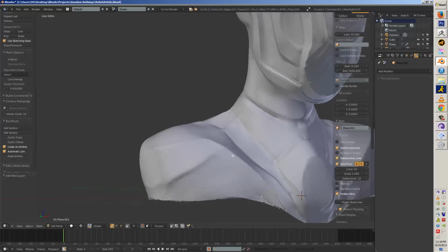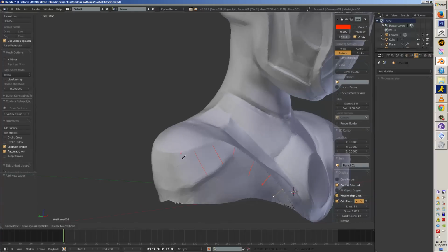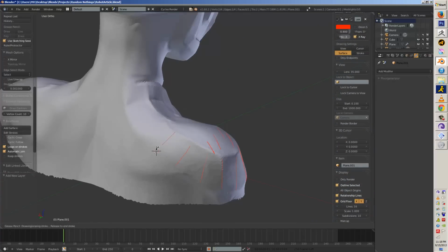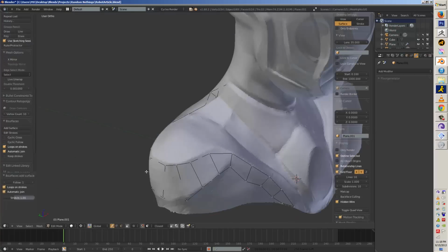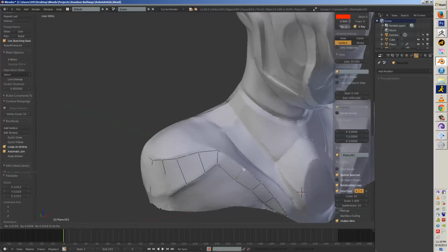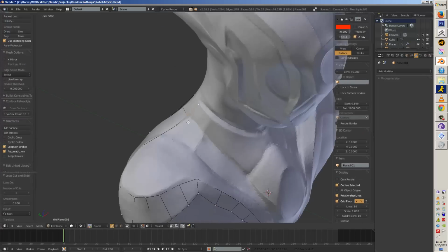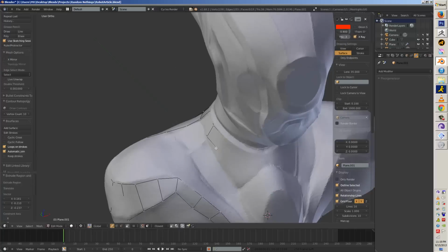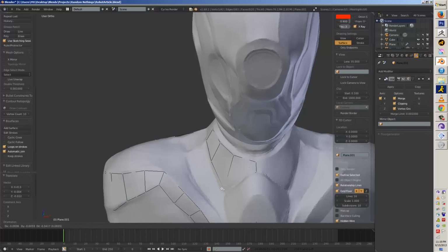And like I said, when I was about to do this without doing the body, that was when I kicked myself and was like, you know, I should just play with some of these topology tools. They're supposed to make it so easy. You know, like B-surfaces, which is one of my favorites. Right there, I knew at the time that I put my pen stroke going the wrong order, so it was automatically going to twist that. But as you can see, just deleting an edge cleared that right up.